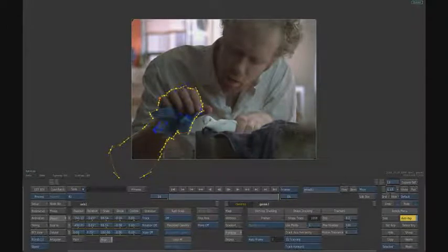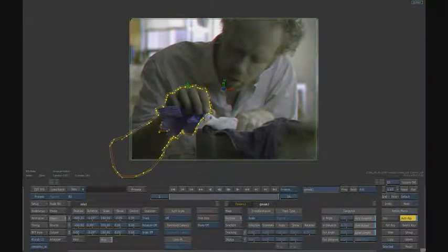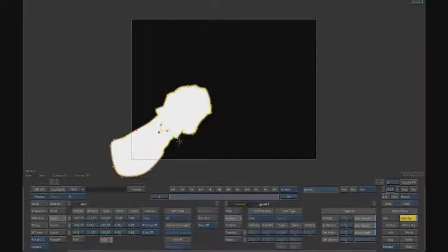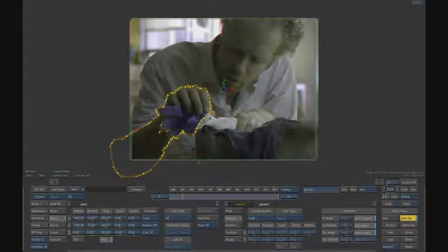And of course I can further refine this if I'd like. I can take a shape like this, pick the edge, and decide that I want to scale up a certain section of my matte. Here you can see I can grow it, adjust it, and tweak a little bit more so you can see how I can even out the edges and tweak in different pieces based on a centroid point, which is really neat. I can also add a nice softness edge here with just the amount of vertices that I think I need, and you can get the idea how we can blend the edges quite nicely.